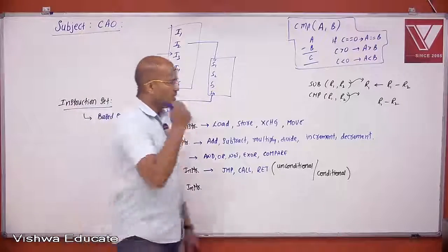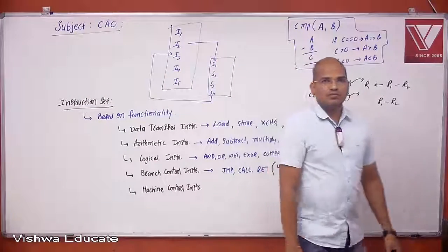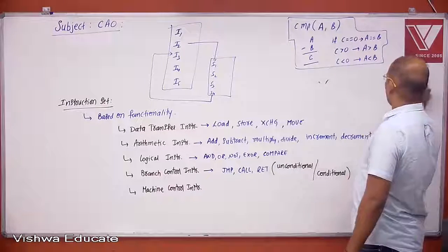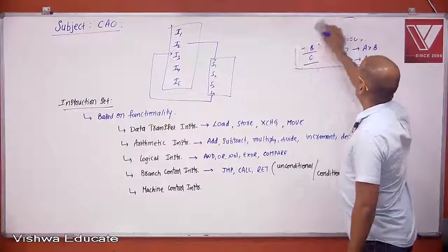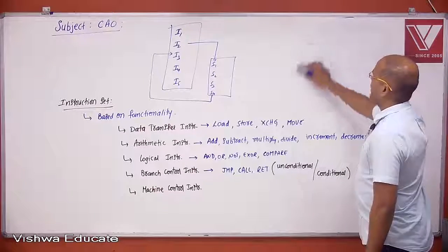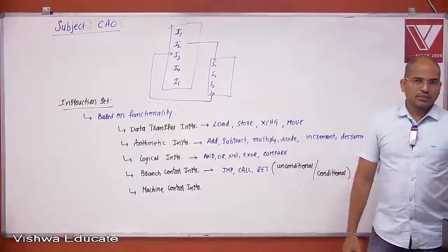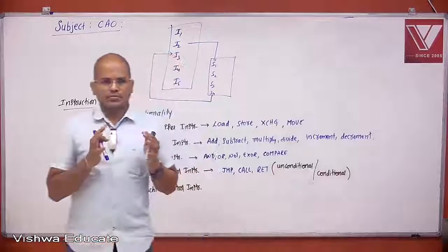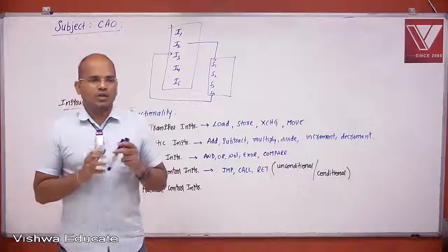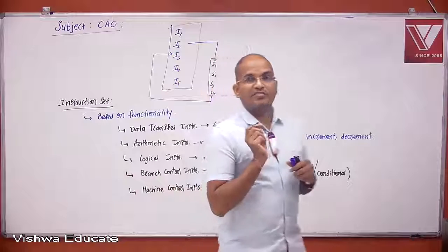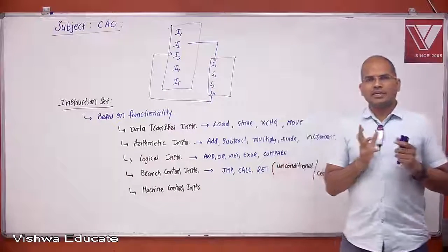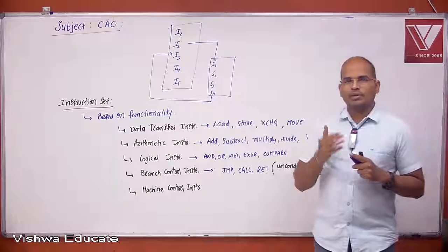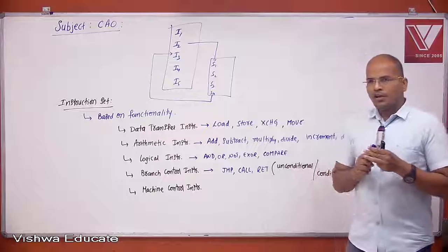Now, what do you mean by conditional call, conditional return and conditional jump? In any microprocessor, we have a concept called the flag register. A flag register contains a set of flags that tell you the status of the current operation being performed.